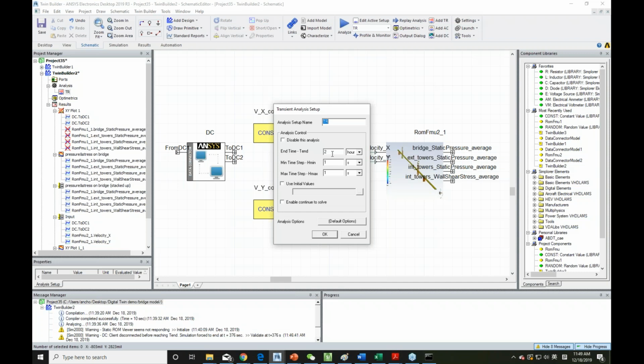You're talking about 4 hours in the future. So what I would do is just specify the simulation time as 4 hours, and you specify your minimum and maximum time step. This won't take you up to 4 hours. It also depends on how complicated your ROM and your systems are, but it shouldn't take up to 4 hours.